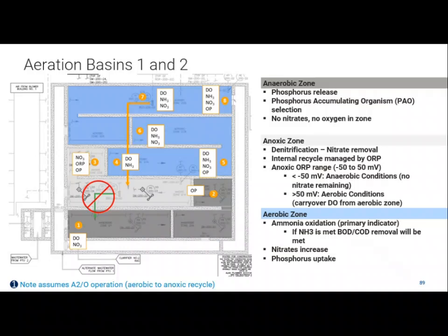What were the flows again? So if you have, I don't think it's actually 5 mgd. I'll just make my math easier. 5 mgd coming in, this would be pumping 15 mgd. Yeah, 2 to 3 times. Okay, so then it'd be at 7.5 mgd. Right? Yeah. I don't know if that's exactly where you're operating at, but it's around there. Like 2 to 3 times the flow rate is typical design.